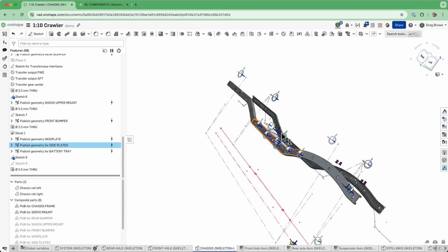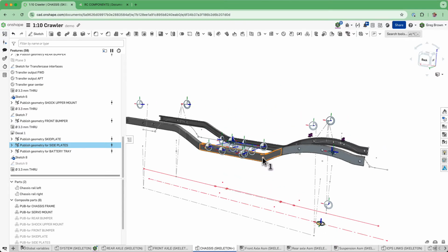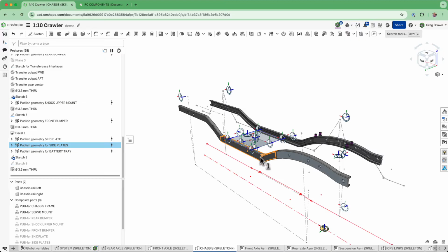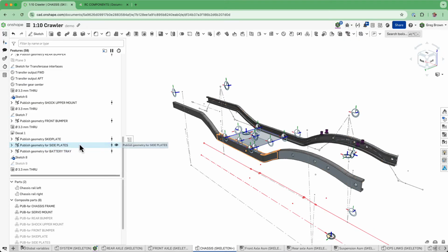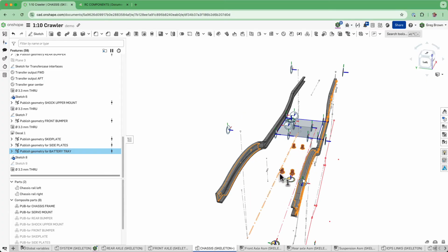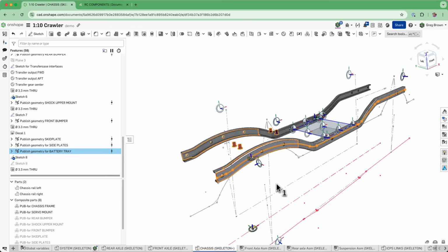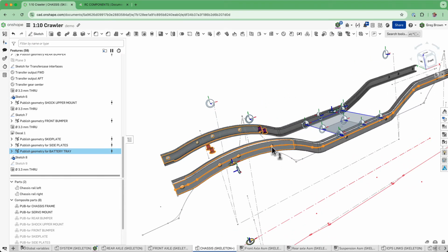We'll attach here, and so I need to know the profile along the side is very, very important, and the height and the depth of this profile here. So all of those things. Oh, and then there's a big one with the battery tray, which does incorporate the servo mounting, the servo axis, and a few other things as well. It reuses these same mounting locations from the suspension uprights. So that is what we do in a skeleton model.